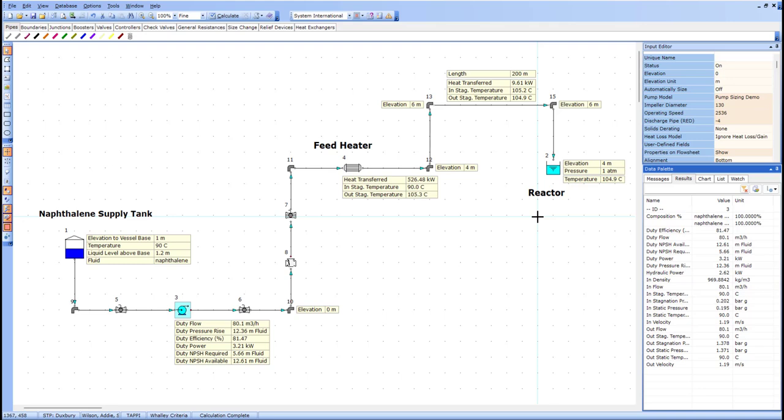This case study highlights why pump and pipe sizing should never be treated as a series of isolated calculations. Pipe size influences pump performance, pump selection affects operating efficiency and NPSH, and thermal losses can determine whether the process remains operable. A systems design approach brings these factors together, allowing you to optimize the hydraulic and thermal performance of the entire system, not just its individual components.